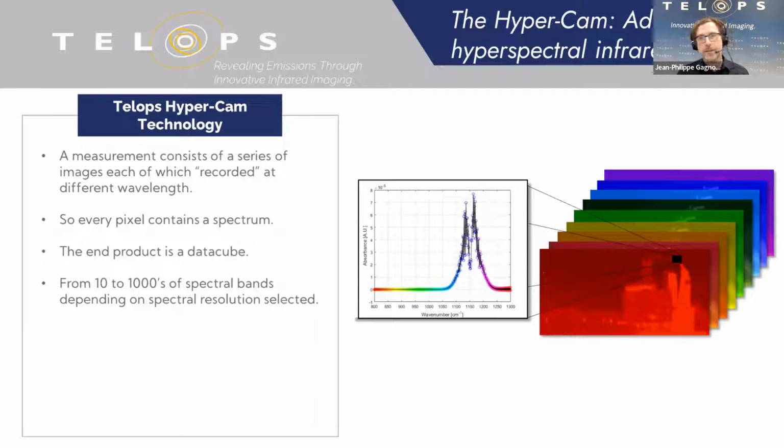So what this translates to in real life is that for different compounds, because each compound has its own signature, you can really look at the signature or lab measurement signature and determine which kind of precision you need, which kind of spectral resolution you need. So for gases that have a broad signal, you can allow yourself to record broad signal. Or if the gas is very narrow, has narrow spectral absorption features, then you can tailor the camera to measure optimal data.